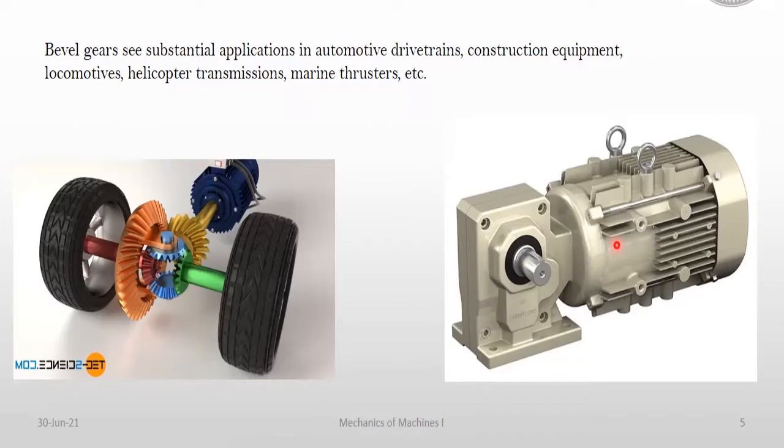Maybe in automobiles they don't have the restriction, but in many other applications, like marine, helicopter, or construction equipment like excavators, they can use this kind of bevel gear drive. Understand? So it's widely used, but the drawback of this bevel gear drive is that it's expensive to manufacture.